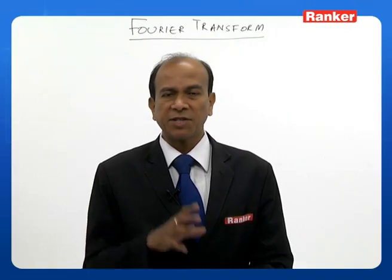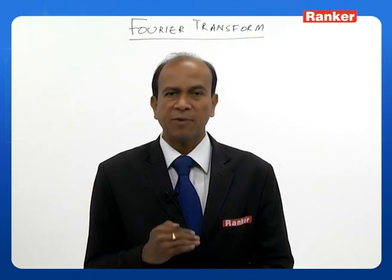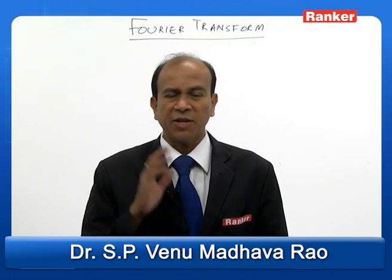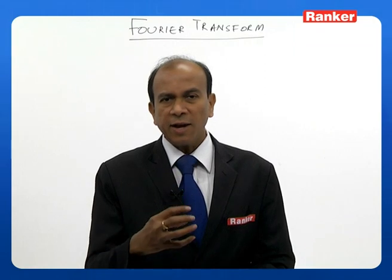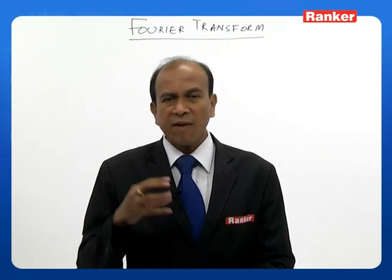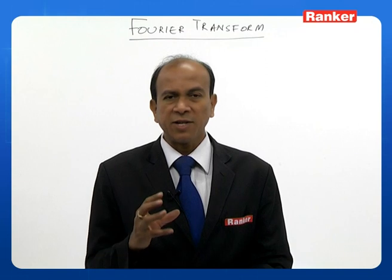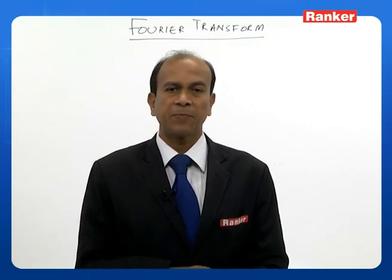Now we have an energy signal g of t. We all know that energy E is equal to integral from minus infinity to plus infinity of mod g of t whole square dt. This will give us the energy of a particular signal g of t. Now when I calculate the Fourier transform of this, I will get the spectrum of energy signals. If I calculate the area under the curve of a spectral curve of an energy signal, it gives me the total energy present in the signal.